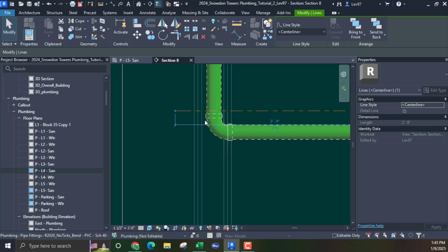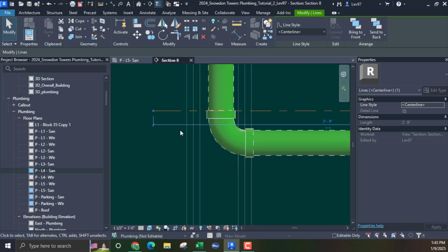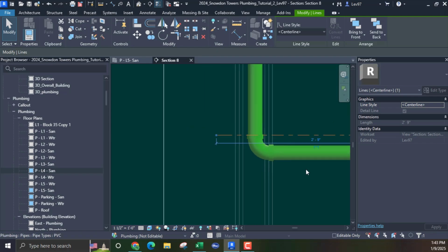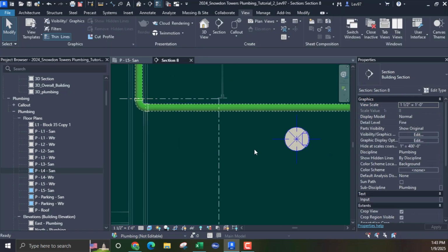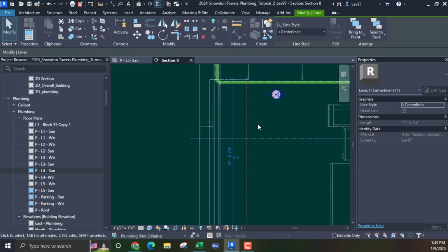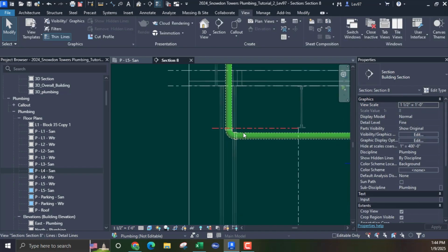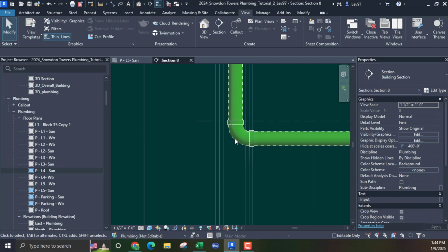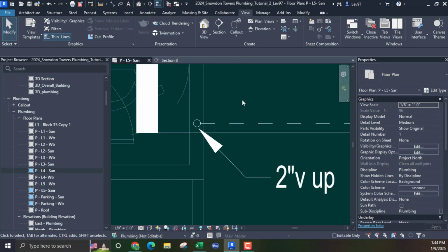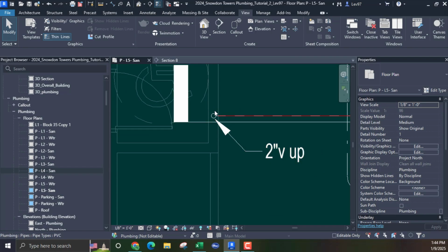But if you can see that, if I go right below it, so now my distance is, say, 11.5. Let's do 11.4. So if I go 11.4, which is below this elbow, let's go back. I'm going to show you guys what happens, why your up symbol and your down symbols are not showing. It has a lot to do with fittings and your view range, of course.